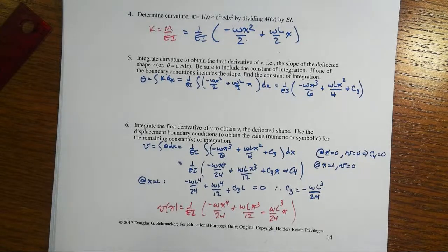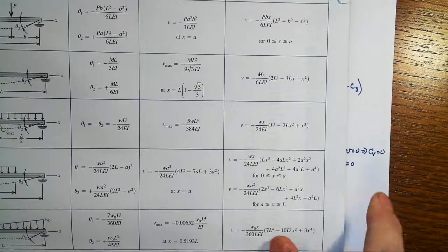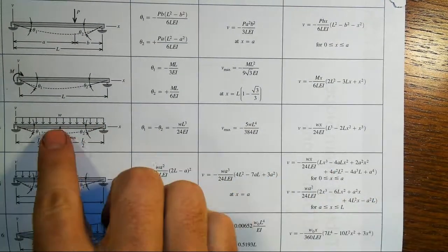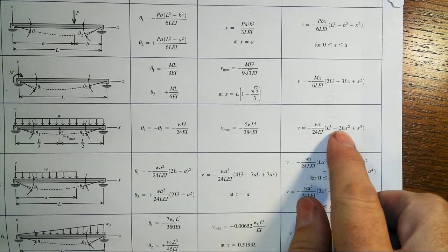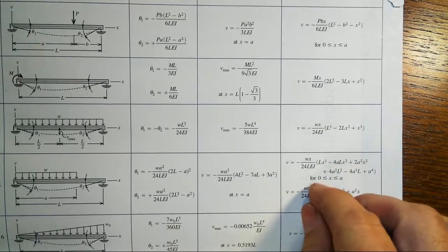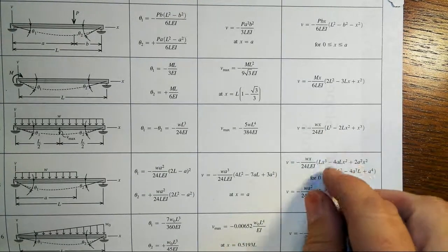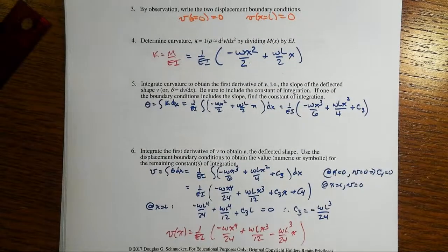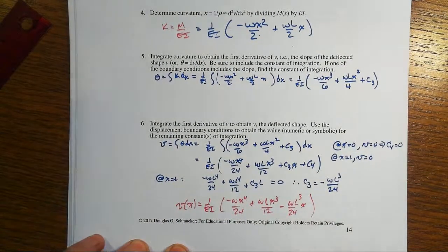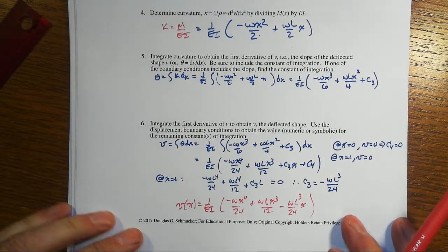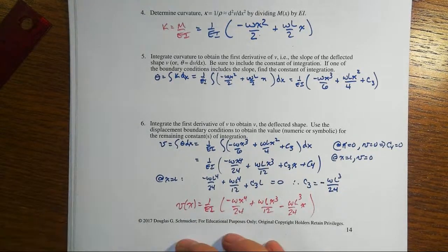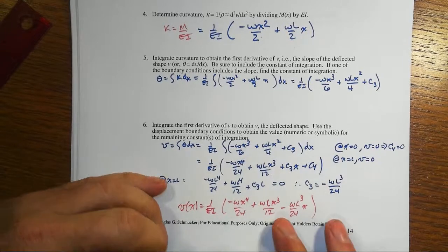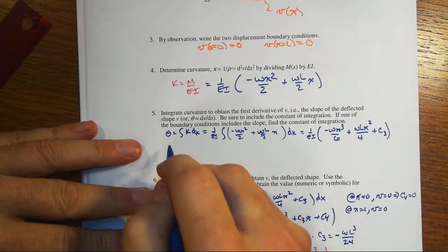Right? Now before we go on, let's just even check this with another version of all this. And you come along and you see here, simply supported beam, distributed load, W positive downwards, we get V equal to minus WX over 24 EI. There's your L cubed, there's your minus 2 over 24, which would be 1 over 12. Right? A minus times a minus, that would make that middle one positive, so on and so forth. In other words, this expression is identical. Same W, same meaning of W, positive downwards. Right? Now, if you looked in there, you saw that we also had the answer for the max displacement, which is 5WL to the 4th over 384 EI. I use it so often, I know it.